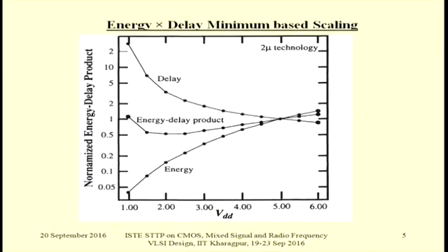Because different functions are accommodated in a single wafer, on a single limited space, people, although they do not express it, always go for a slightly higher VDD value. The energy will be going up. You see that the phone is getting heated, but to a limited extent. The more important thing that they gain is that the delay is coming down.